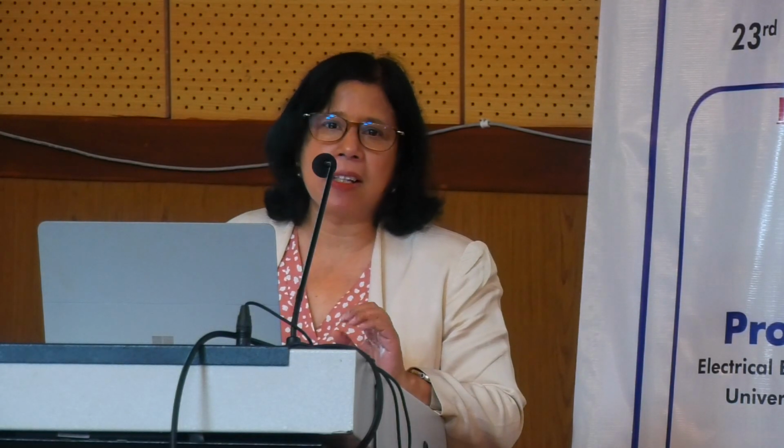So yesterday we talked about a few things. One was the reluctance. Okay, how do you calculate reluctance in a magnetic circuit? One thing we need to remember is that for calculating reluctance, we must know the permeability of the material. And if we have saturation, then permeability is no longer a constant. So in that case, if we use reluctance or an equivalent magnetic circuit, it does not give us an accurate result. It will underestimate the flux.